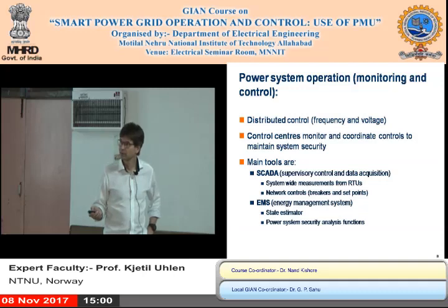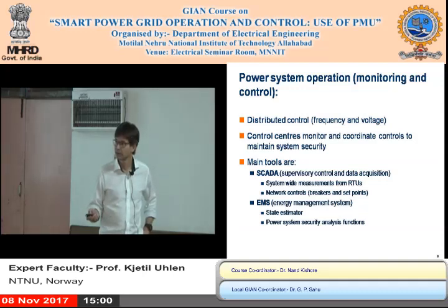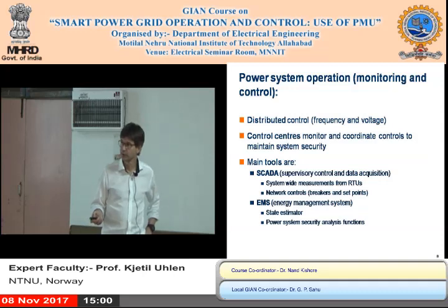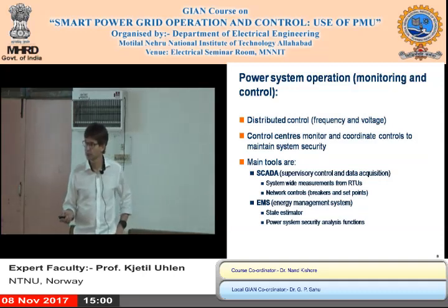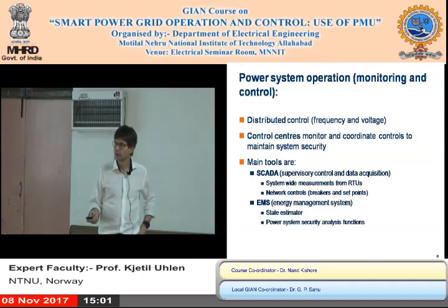So we need enhanced information that is available with phasor measurement units. You could use that with respect to determining the limits. You could, for example, use phasor measurement for state estimation. You use wide area monitoring tools to monitor your limits, or to know your limits.